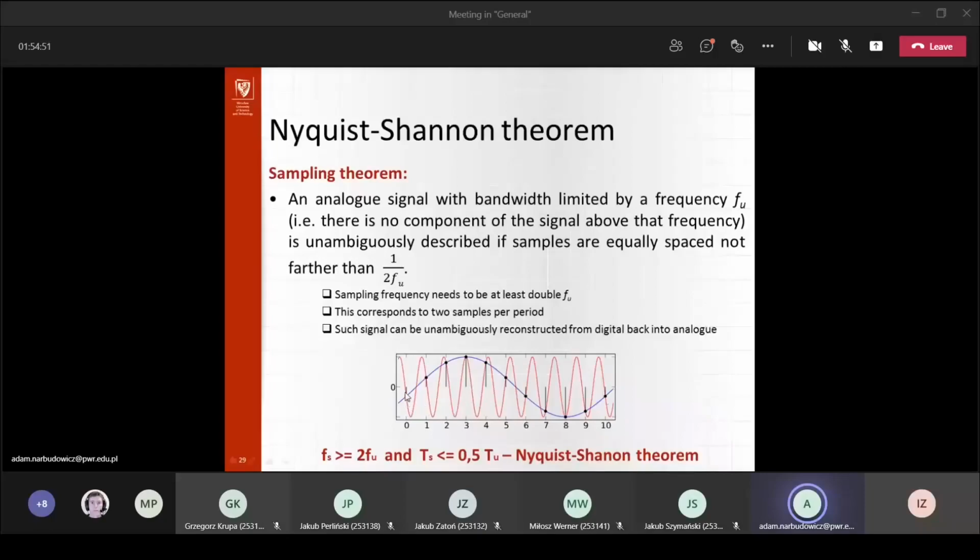And what hopefully you can see is that if you just take the set of the black dots over here, without satisfying the Shannon sampling theorem, or without the information about the upper frequency, there are actually more than 2 signals that could perfectly fit that curve, right? So at the end of the day, we don't really know which one of those 2 curves is being transmitted, right?